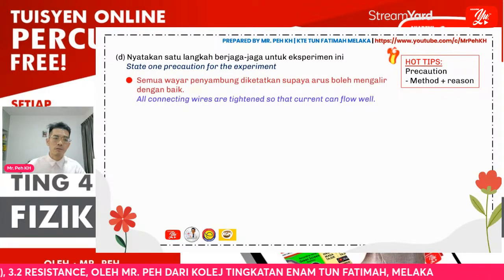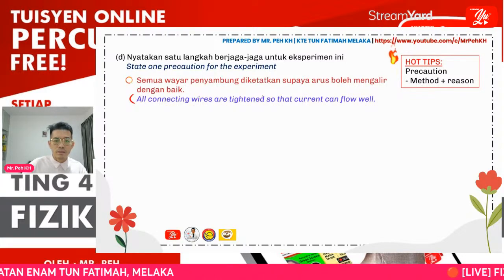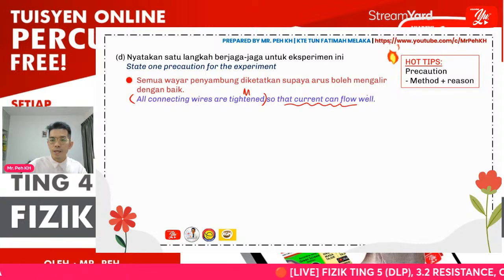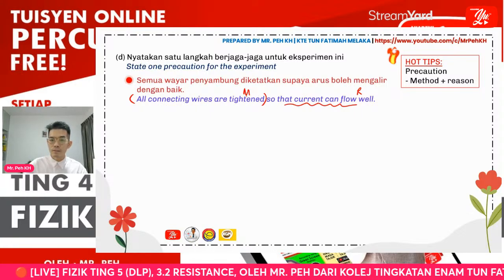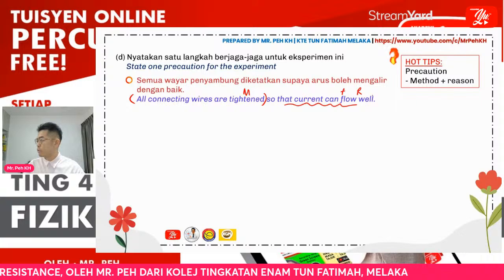You can see the method here: all connecting wires must be tightened. So this is the method, and the reason is so that current can flow well. Okay, so make sure you give the method together with the reason for your precaution.